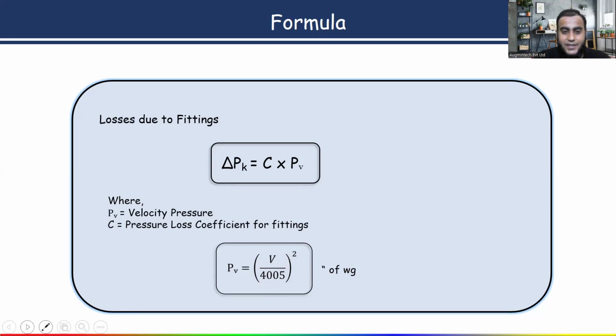Is this clear? Tell me, up to here does anyone have a doubt? Please let me know so we can go further. From where will you get the duct velocity? It is very simple. All of you know the discharge flow rate formula, Q = AV. In this formula, Q is the airflow rate, A is the area of that duct, and V is the velocity.